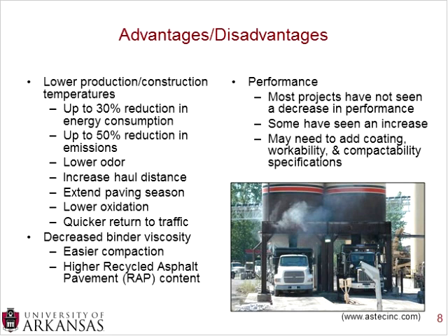Now you also have a decrease in binder viscosity, which means you have easier compaction, and you can also have a higher recycled asphalt pavement content, or RAP content. And then finally, going over to performance. Most projects that I've read about have not seen a decrease in performance. Some have seen an increase. So there's some sides to both stories there. And really the only disadvantage I really see at this point is from a specification side.